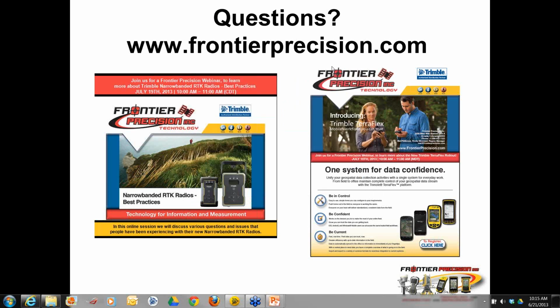Yes, we would encourage you to use a feature code and attribute library, and in there assign a photo point. When you take your measurement, the attribute would pop up, and from that attribute, by using a photo point, the camera function would be right there, and you would actually be linking that photo to that point. And then when you send that into either Autodesk Map or ArcGIS, you would have that attributed information plus the photo point. Excellent question. We were just trying to keep it simple here, using the snap tool that Jay showed, going to manually assigning it to a point.